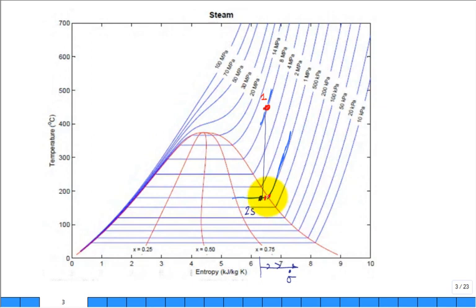And so the actual state may still be in the two-phase region. It may actually come out saturated vapor if it just luckily lands right on that point. Or it could come out superheated. You're going to have to check.